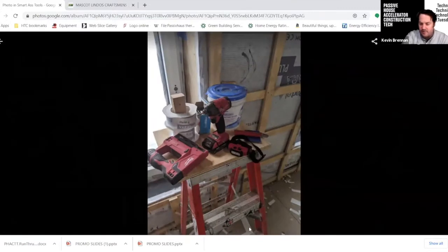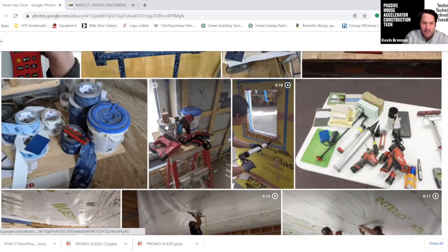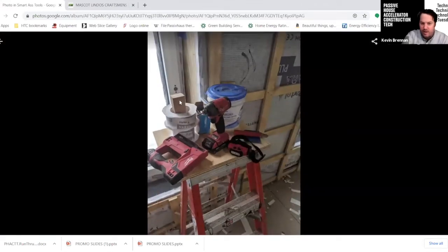This one here is the cool tool, or the way that we did one job where we had a 4-foot ladder, and on top of the 4-foot ladder, we mounted a piece of plywood, which was our roll holder and our cutting surface. We were installing membrane and tapes there, with a headlamp as well, press fix, knife, wipes, everything all in one location, so you're not going up and down. The innovation that happened there was adding the 2x4 or the 2x3 to stop us from continually dropping the roll on the floor, which is a pain.